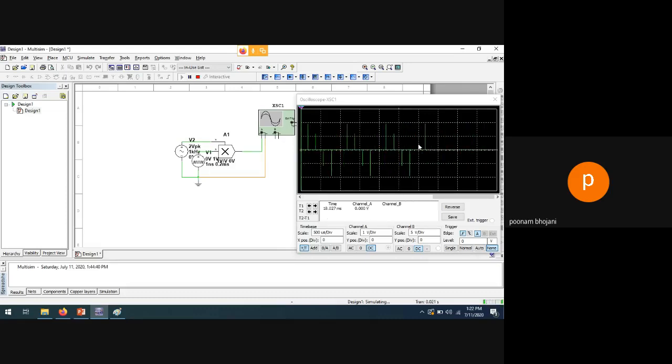So at the receiver side, can anyone get the original signal from this type of sample? That is either a sine wave or a triangular wave. If you join all these samples, you can get a triangular wave also, right? So at the receiver side, the original signal cannot be reconstructed if the number of samples is very small. If the number of samples for one cycle is very small, then reconstruction at the receiver side is not possible.